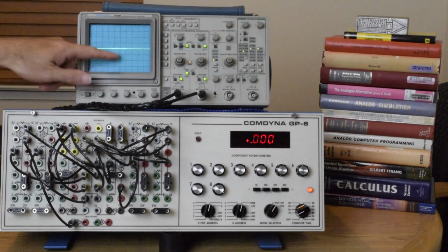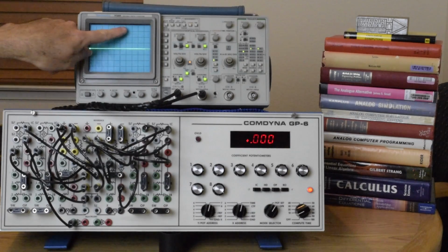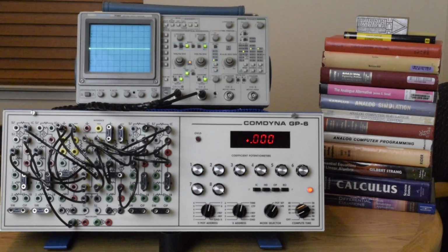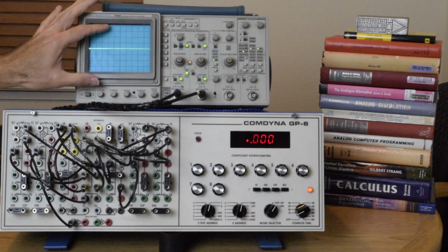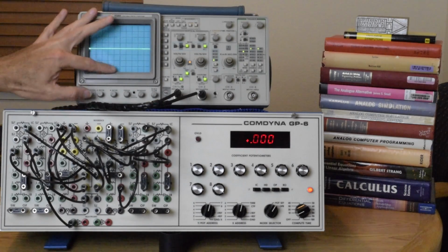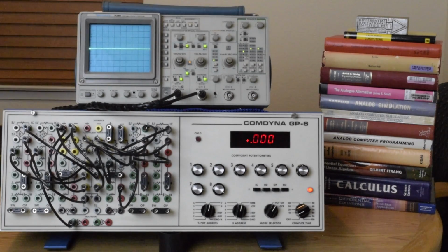And then on the y-axis, we basically have minus 10 volts to plus 10 volts excursion here, and that's another part that makes this a little confusing with a modern oscilloscope, because on the grid references there's only 8 grids in the y-axis, but there are 10 grids in the x, or actually t-axis. So that gets a little confusing, and even confuses me at times. But we can take a look.